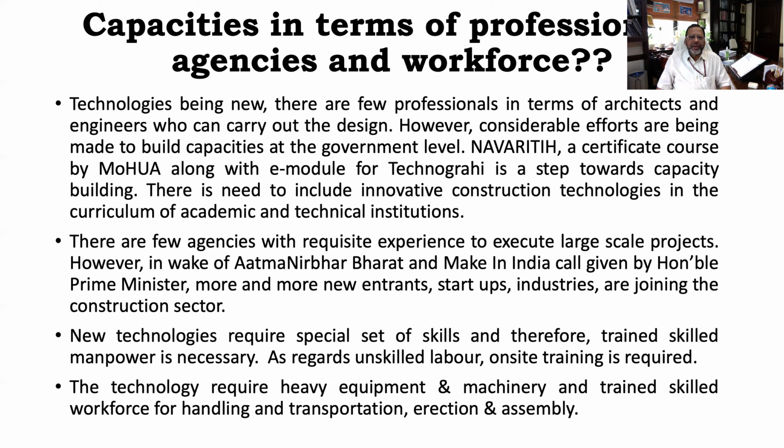Also, because it's a heavy formwork and you require heavy equipment and machinery, a trained skilled workforce is required not only for construction purposes, but for handling the formwork, transporting it to the site, erection and assembly of formwork, then taking it out and taking it to the other floor. And it has to be done in a sequential manner, so supervision and skilled workforce is also necessary. Most of the agencies can impart on-site training to the manpower so as to make them skillful to undertake the project.